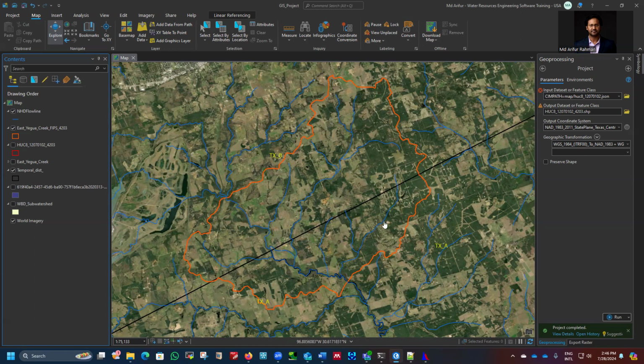And yeah, that's the way we develop our HEC-RAS 2D model. So in the next video, I'll set up the dummy HEC-RAS model, and I'll also create an empty geometry. I'll also process land use and soil data to generate the infiltration layer. So that's the second step.